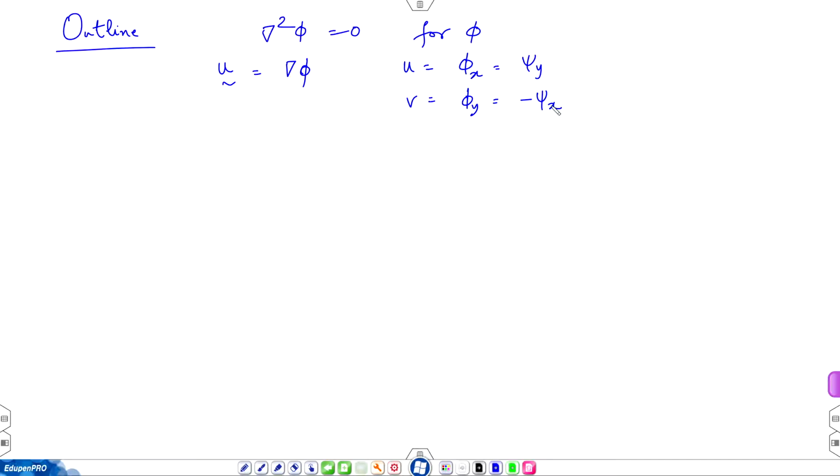Now, what is the structure of that flow field? That can be examined by looking at the streamlines, and each streamline is psi equal to constant. Therefore, you have to find the stream function. So, if you know phi, then through the velocity field you can relate phi to psi as shown. Here I have used Cartesian coordinates. You have similar expressions in polar coordinates.